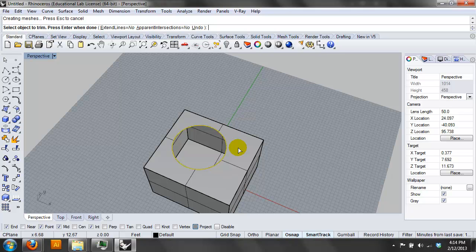Split the box surface with the cylinder? Yeah. You can. I'm just saying there's multiple ways to do it. This is clear because it makes the intersection of the curve, and it uses it to make the trim. This is a nice technique to know though, because remember I said you go from curves to surfaces to curves to surfaces. So you take the curve from the surfaces, use it to trim to make a new surface. Okay.